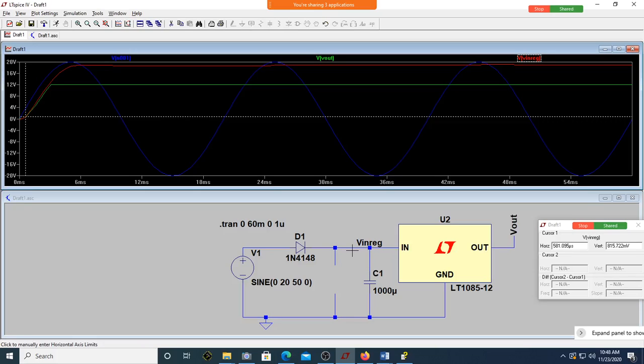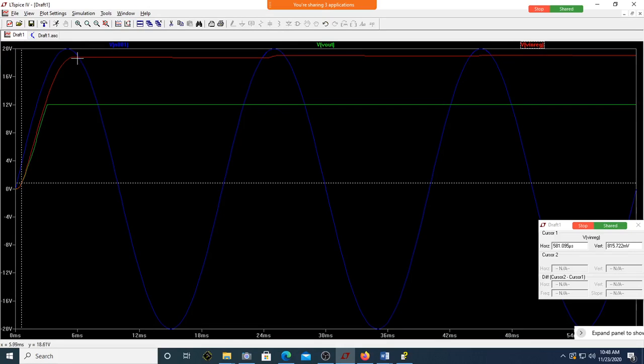Sir, the resistor is only needed when it's discharging. Due to the internal resistance of the IC. Okay. Now, the resistor which was there was actually providing only the discharge path for this capacitor. That is still available in the form of the input impedance of this regulator. You can see this is still reducing. Can you see this voltage?